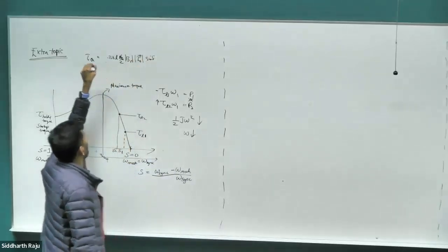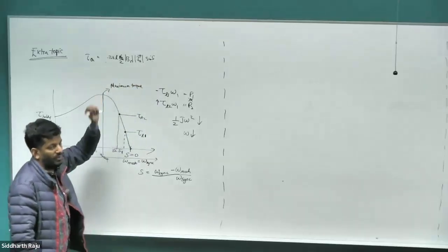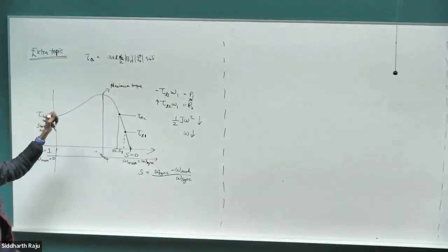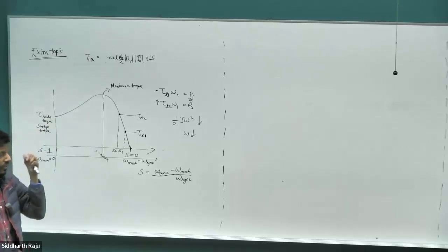So for a fixed current, the torque increased as a function of delta. On the left half, when delta was less than 90 degrees, the same thing was happening. When you asked for more torque, the rotor fell behind, in turn creating more torque, which led to a stable equilibrium point where it could operate with the new delta angle.